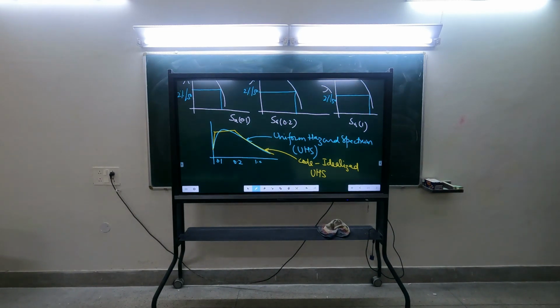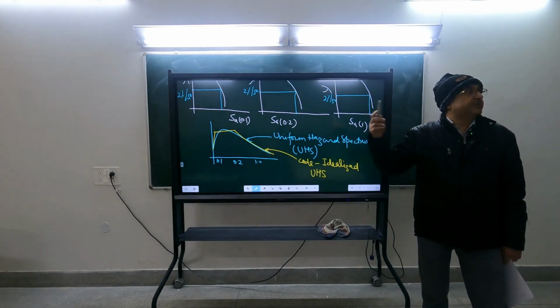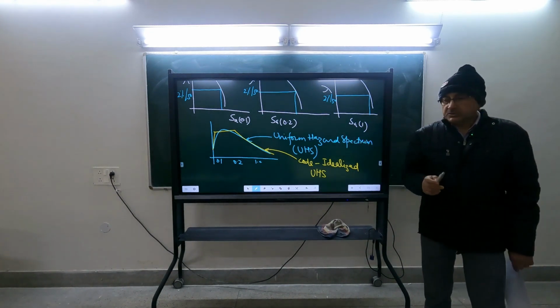We have to keep this in mind, and we will use it when selecting ground motions. While selecting ground motions, you have to keep in mind that one single ground motion is not going to give you this shape. The shape of the response spectrum of the ground motion will be different, because it is not representing one earthquake. It is representing the envelope of several earthquakes.